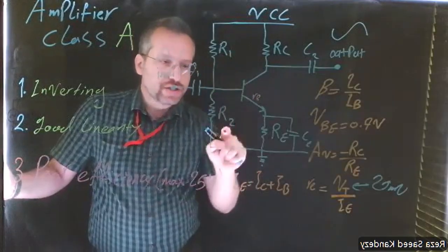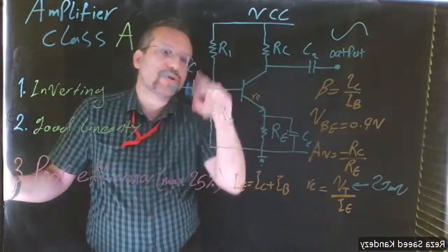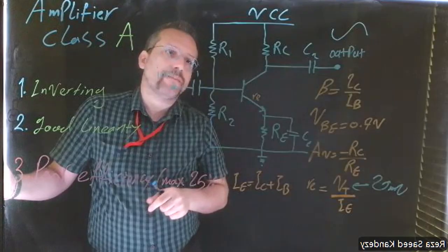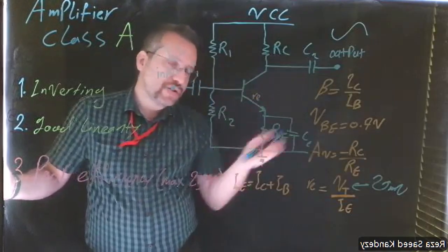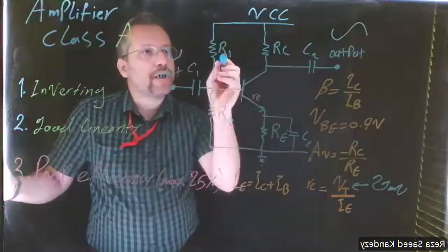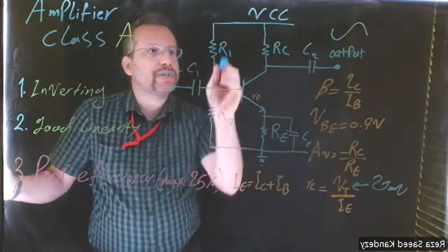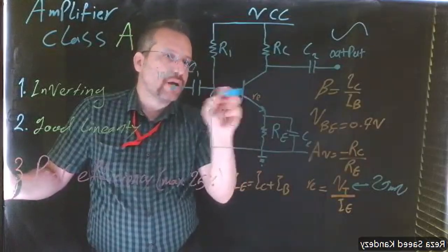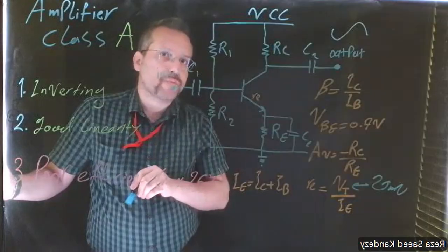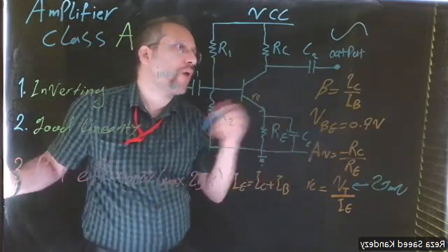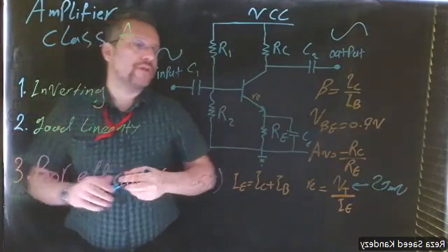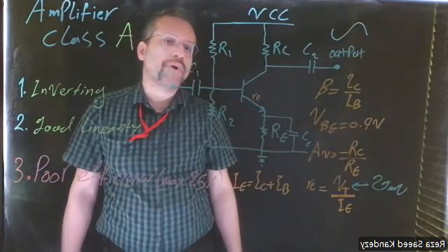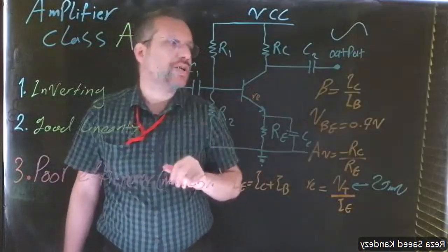In this specification, you can use different types of biasing methods. The circuit that we drew here has voltage divider biasing. These R1 and R2 are the voltage divider that helps us bias the base, and basically the whole BJT. Now, let's remind ourselves about some of the equations and components that we know about the BJT.